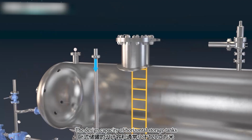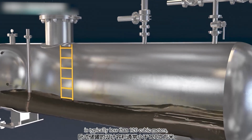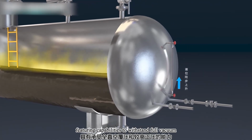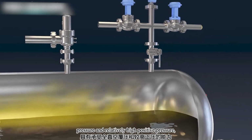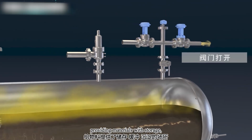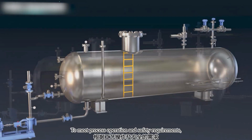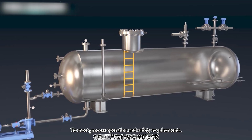The design capacity of horizontal storage tanks is typically less than 120 cubic meters, featuring capabilities to withstand full vacuum pressure and relatively high positive pressure, providing materials with storage, buffering, and sedimentation space to meet process operation and safety requirements.